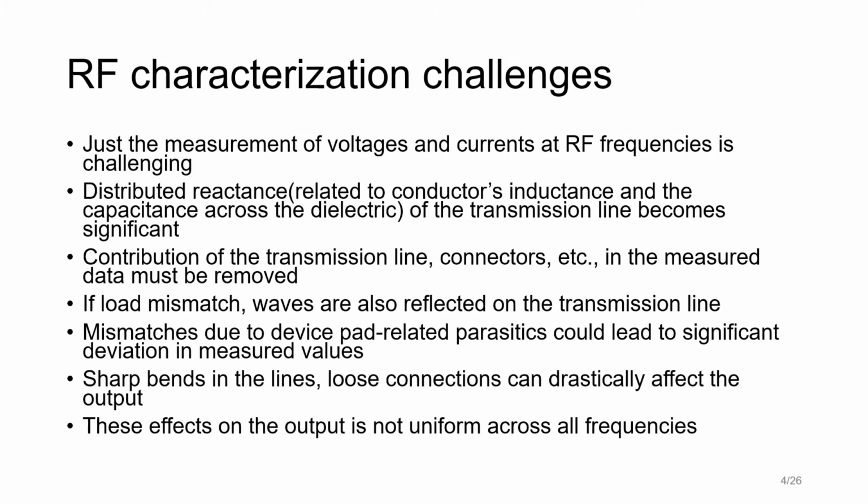And it is not only about the cable, but anything else that is a part of the test setup as well. That too contributes to the final response as seen by the measuring instrument. So for example, the connectors too can contribute to this. And it is not only about the accessories and the things that are part of the test setup, but also the other parasitics that are associated with the fabricated device. For example, the large pads and their pad capacitances also contribute to the final response that the measuring instrument sees.